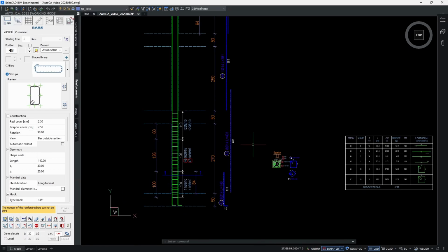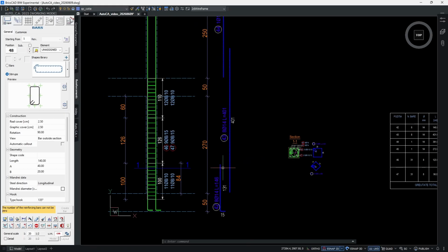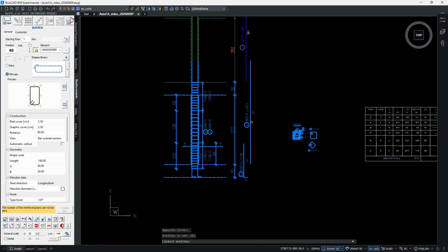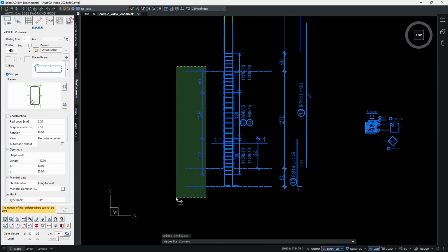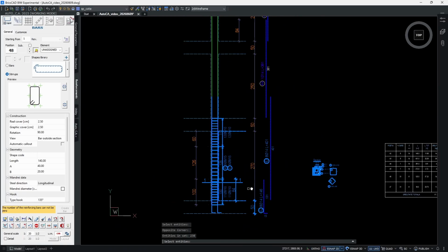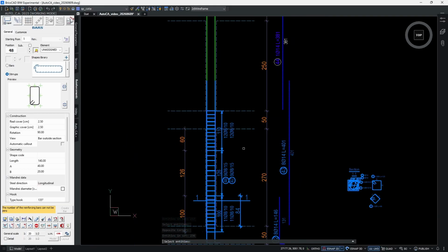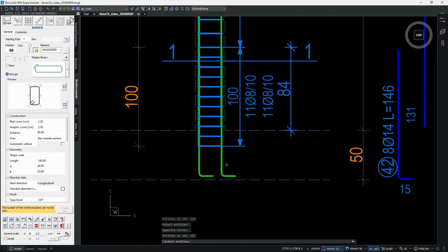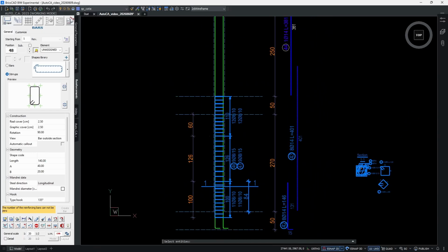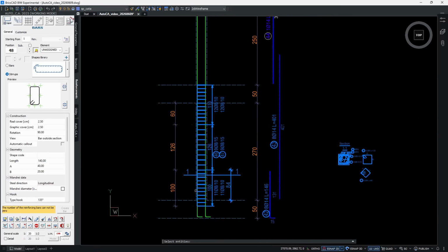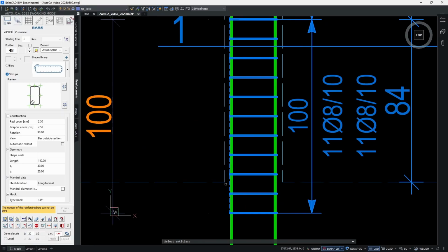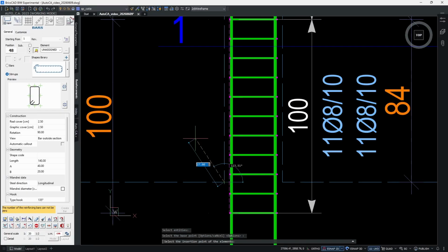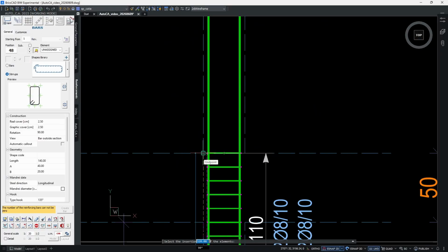Now that we understand the core properties of copying, let's continue with the column. By using a properly selected reference point, we can capture all existing bars and copy them one floor up. We need to exclude the longitudinal bars and the polylines selection, also the side longitudinal bars. And yeah, we have everything selected. And now I'm gonna choose this point as a reference point. Okay, and I'm gonna move everything up one floor.